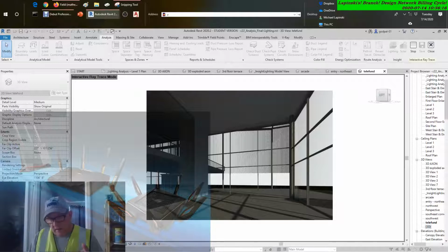Clicking to create the energy model, Revit builds it from the information in the previous sections of your model. This process can take a bit of time. As a warning, Revit will provide you with a dialog box noting that it will not be accessible during the computation time. Click to create the energy analytical model to continue.